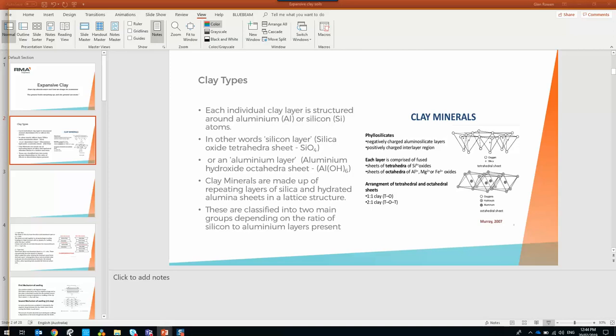So here's one I've prepared earlier. This is WeWar. It's a big shed, 60 metres by 180 metres, and to fully suspend it on black soil is just ridiculous. So we've done around the perimeter, and that bit jutting out the top is offices, and because it's got partitions and stuff that's sensitive to movement, we suspended that as well.